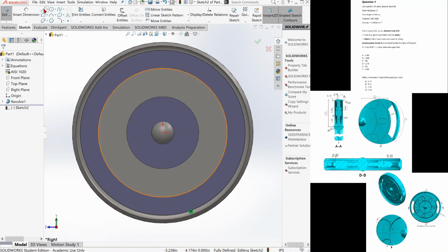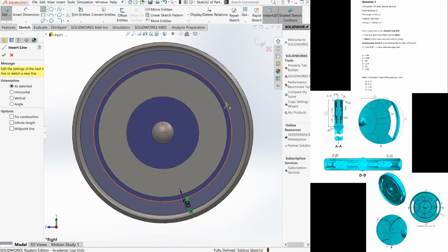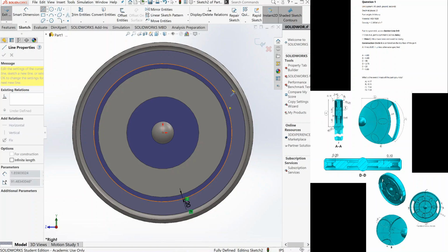Okay. Now you're gonna use your line tool and make it coincident to that protruded line, the offsetted line, and then connect it to the circle. Don't worry. I know how this line is going crazy. That's because of a tangent property it has when you connect on a circle. Don't worry, we'll delete it later and we'll fix it. Just make sure it's coincident to the offsetted line and coincident to the converted line.